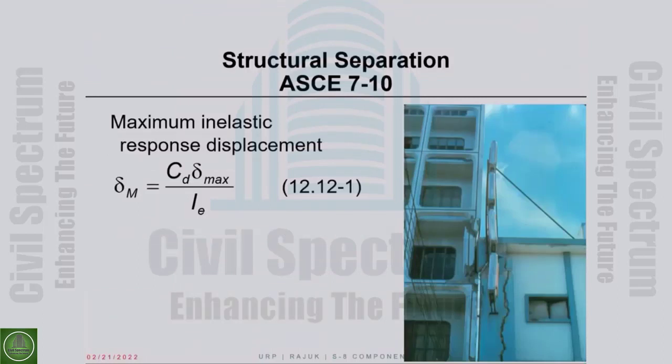Okay. I think I have shown you this picture from the Mexico earthquake of 1985. And the point of the picture, and this is always true, in this business of hammering, the most important thing is whether the floor levels of the neighboring buildings align or they don't. In this picture, they are not aligned. So the heavy floors of the right building hit not quite mid-height, but along the height of the column of the next building. And after a few poundings like that, the column gets damaged, and then a whole portion of the building can come down.